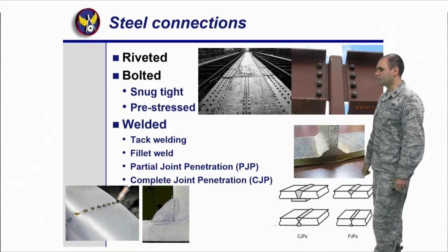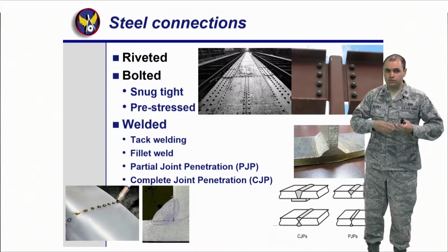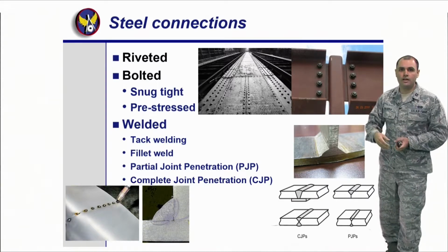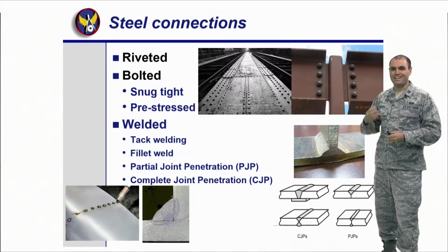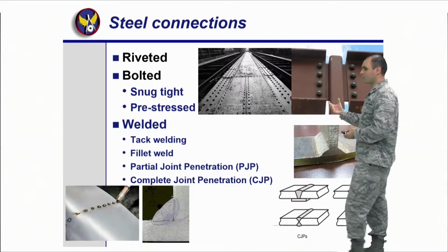And now I'll talk to you about steel connections, right? So I told you that one of the biggest aspects about steel is how it's connected. Steel is great, but the connections are usually its weak point, right? Because that's where it got cut, somebody tried to manipulate it, it got heated maybe, or something happened, it got dented. So there's a lot of different connections.